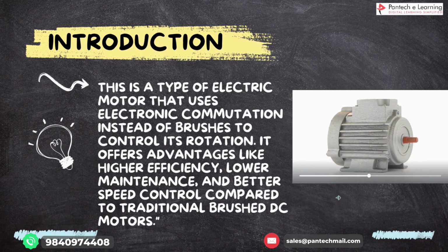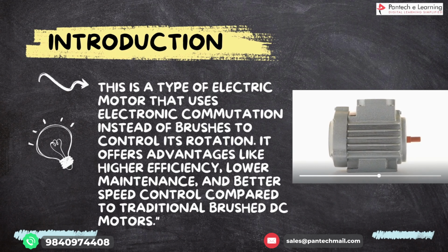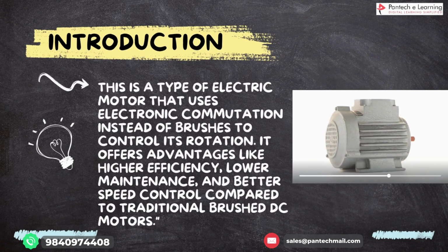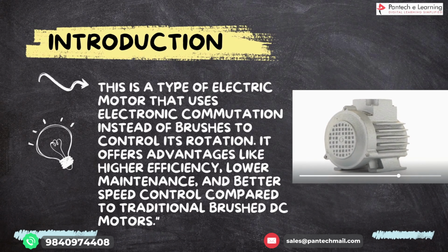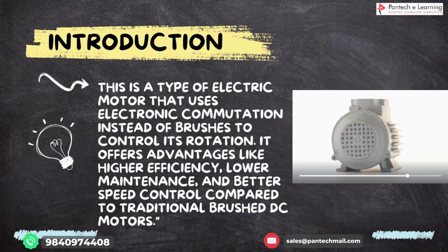I have to tell one thing. This brushless DC motor often has a Hall effect sensor mounted on the stator part. These sensors mainly detect the rotor's position by monitoring changes in the magnetic field. This information is sent to the motor controller part, which determines the appropriate phase currents and timing for the commutation purpose. Next one is the speed control of brushless DC motor.